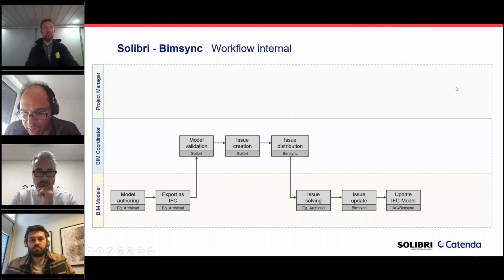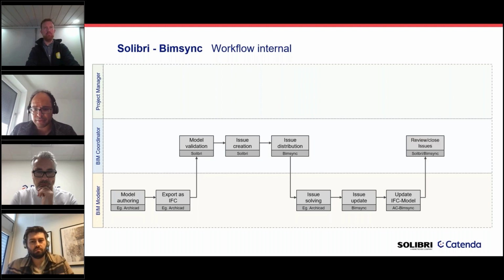Right, I will update the IFC model and send this updated model back to the BIM coordinator, because I have updated the issues as well as the IFC model. The BIM coordinator could choose where he wants to review and close this issue. He could either say, I'm doing it in Solibri, or I would do this also in Bimsync, depending on where he is and how complicated the issue is.